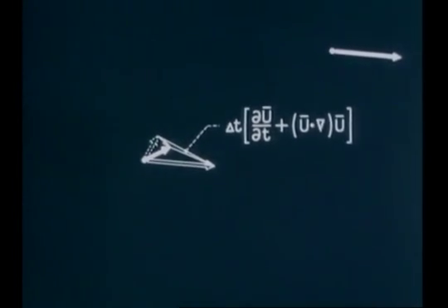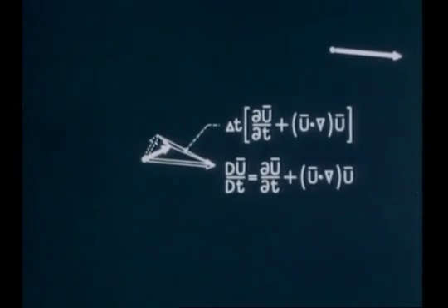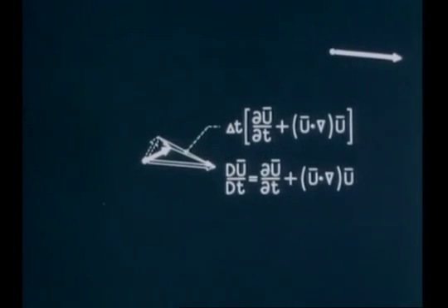The material or substantial derivative is just the expression multiplying the time difference. This is the rate of change seen by the material point as it passes a laboratory point, written in laboratory coordinates. In this way, the acceleration, more simply written in a Lagrangian description, has been expressed in Eulerian notation.